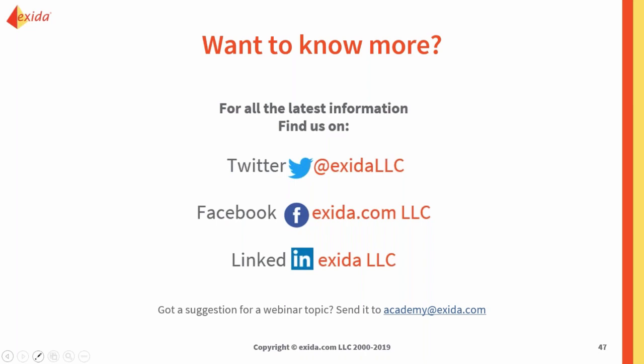Just when you are doing that, make sure you're looking at it closely. A lot of times those certificates will have recommended proof tests coverage and proof test durations. Make sure all of those line up so you are getting the exact values they're claiming. I've seen some certificates where it says you're getting each individual piece, you're putting them together, and it forgets pieces or leaves portions out, or the test interval is so unrealistic, it's invalid. So when you are doing the calculations, look for all of that, but it is absolutely something that you can do yourself. It's a little easier if you just buy it together, but that's definitely, if you're doing the calculations, you're looking at the tables, absolutely.